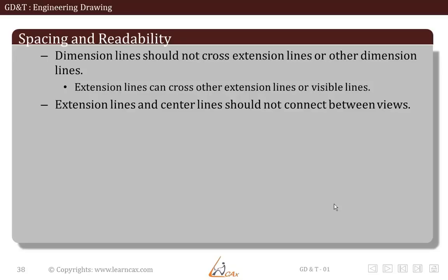That is, when you are drawing orthographic views of a part, like the front view, top view and either of the side views, make sure that extension lines and center lines do not continue from one view to another view. Instead, they should be disconnected between the views.